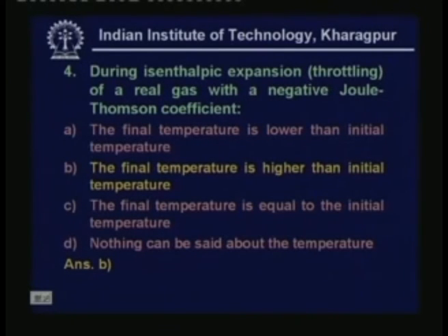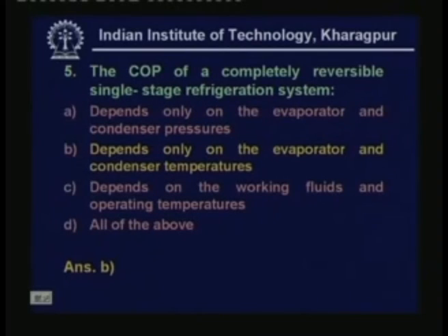Finally, I asked you what the COP of a completely reversible single stage refrigeration system depends on. The answer is it depends only on the evaporator and condensing temperatures. It does not depend on pressures, it does not depend on the working fluids, it is only a function of temperatures according to Carnot's theorems.